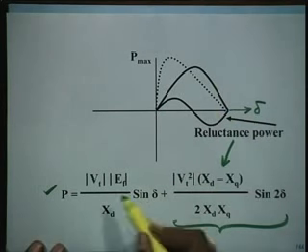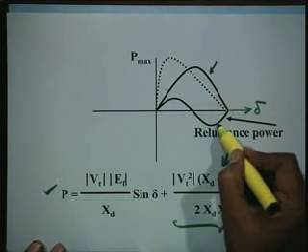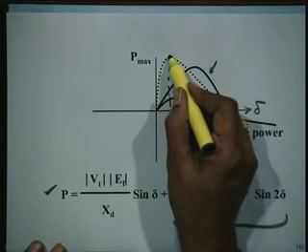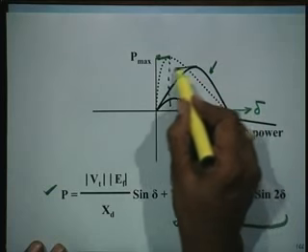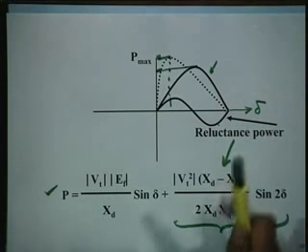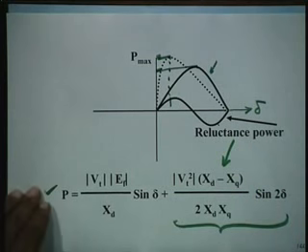So we superimpose the sinusoidal term with the second order term, and you get this dotted curve as a P maximum, which is higher than the P maximum of the cylindrical rotor machine. So you get extra power. In fact, there has been machine design based on this principle called reluctance motor, which runs on only reluctance power, which you might have read in the machines course. Otherwise, you can see our machine book or any book.